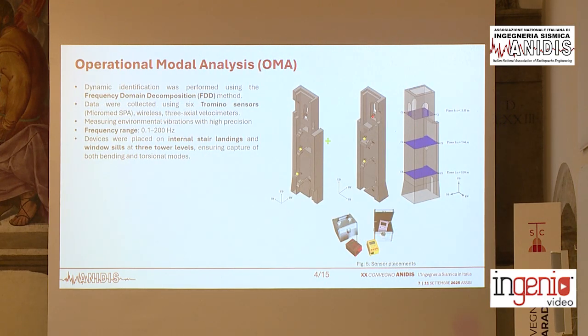For the dynamic identification using operational modal analysis, frequency domain decomposition was used, and this research takes advantage of the results of the previous study. Six velocimeters, Tromino sensors, were mounted at three levels of the height of the structure in order to record and capture both bending and torsional shapes of the movements of the structure.